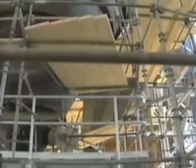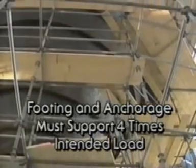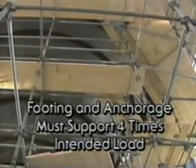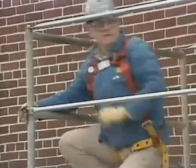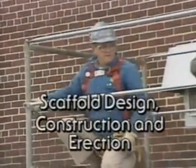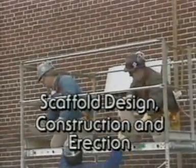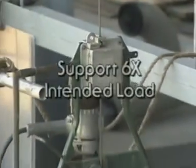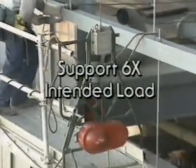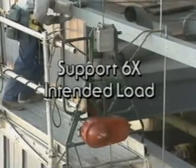All stationary, upright, or mobile scaffold components must be capable of supporting at least 4 times the maximum intended load. Every scaffold should be erected on a level and firm base under the supervision of a competent person and then carefully inspected before being put into use. The wire or rope holding up a suspension scaffold must be capable of supporting 6 times the maximum intended load.